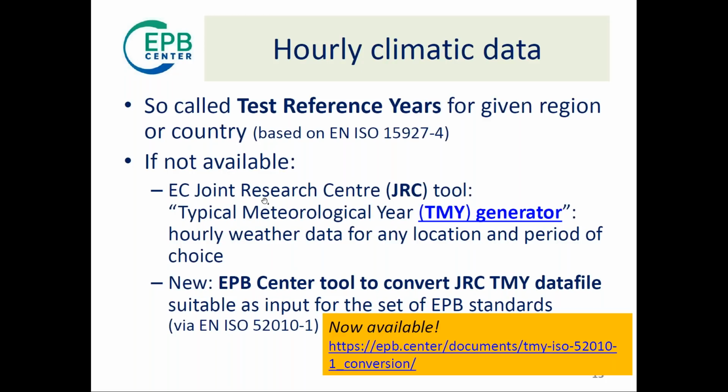So the hourly climatic data were also mentioned in the previous webinar, and so we said there you can use test reference years for a given region or country. If not available, you can use the recently developed typical meteorological year generator developed by the Joint Research Center of the European Commission, which gives you the hourly weather data for almost any location and period of choice.